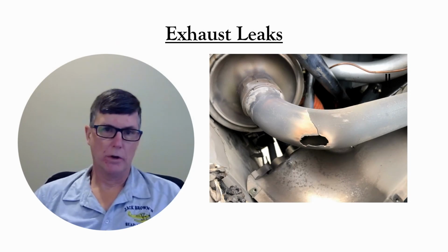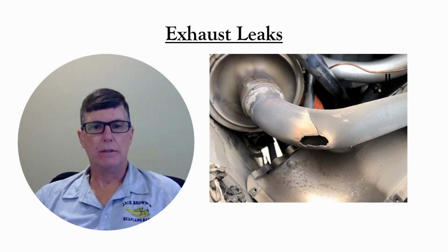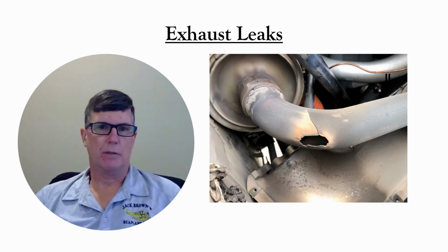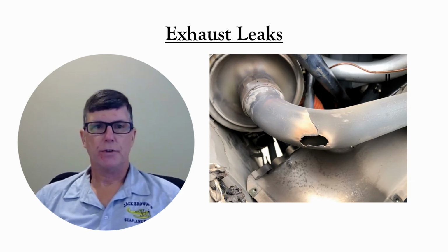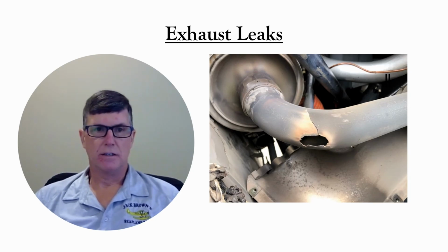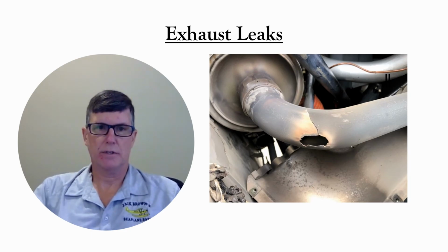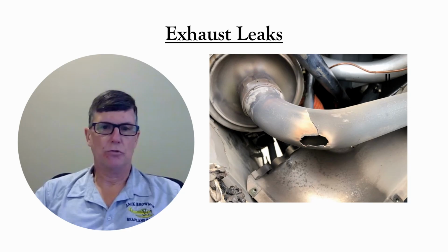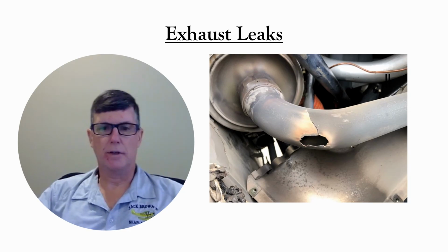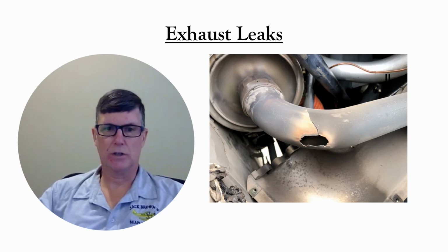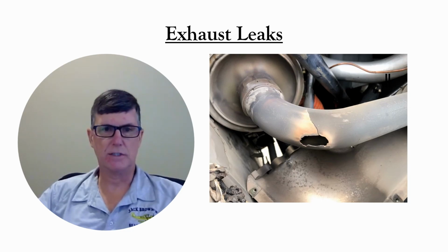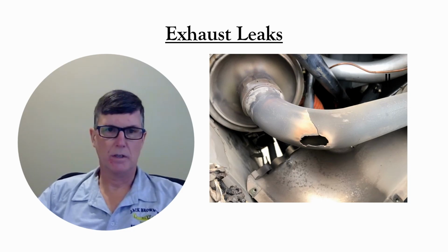One thing that can go wrong in an exhaust system is that some of the parts can develop leaks. The first indication of a leak is a tan-colored discoloration around the leak. So that's something that you should look for during your pre-flight inspection on all of the exhaust system parts that you can see during the inspection.